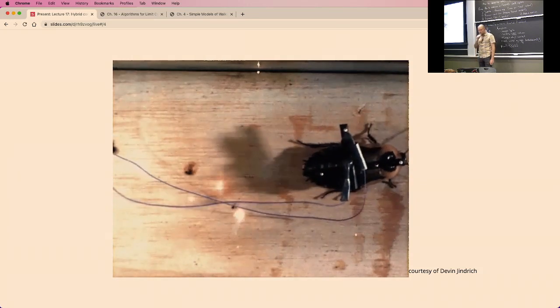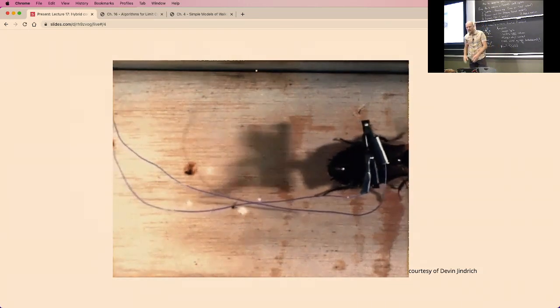And one of the beautiful things in that study was his observation: in the vertical view of the trajectory, it looks like it stabilized pretty quickly despite a pretty big perturbation. But actually the orientational velocity of the cockroach stabilizes within a step, and faster than they think the neural response of the cockroach could possibly be. So their strong argument was that it's actually the mechanics of the leg implementing spring models in order to stabilize the cockroach in the lateral direction, which is pretty cool.